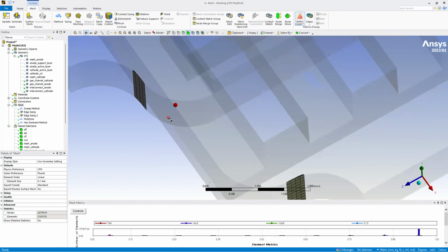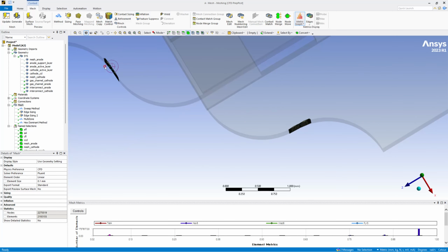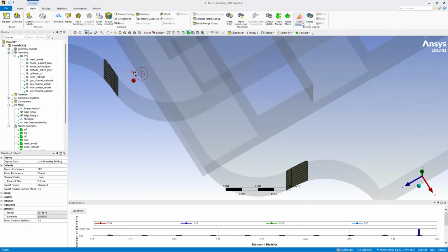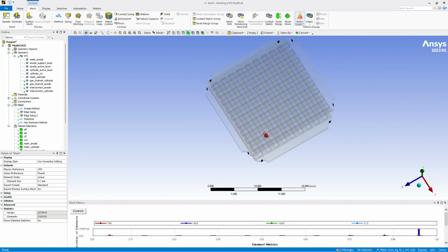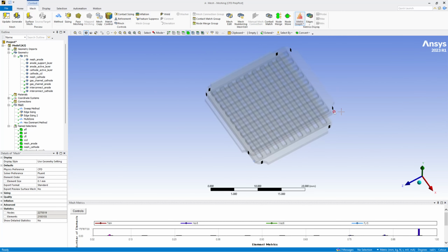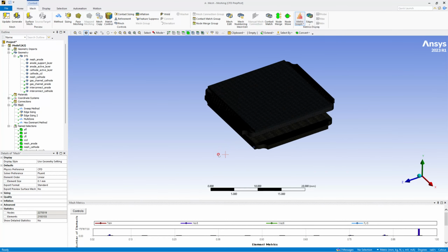These have the worst quality, because they don't look anywhere near a hex. So they can make some real issues when the flow is being solved in these regions. Overall the meshes have very high quality, but there are low quality elements as well. So we will address them in the next session when we move towards the map meshing.